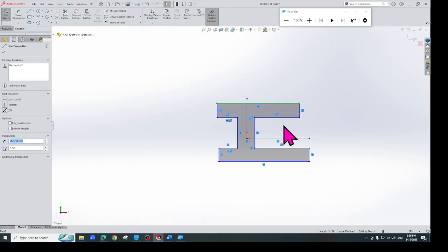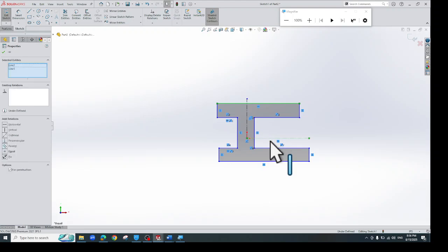I mean, you should hit Ctrl to select the horizontal center line and this edge of the below rectangle. Then you will see that the selected lines turn green. After you select these three lines, make our model symmetric around the horizontal center line.